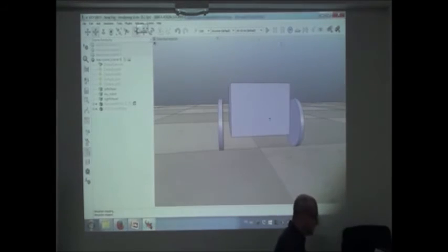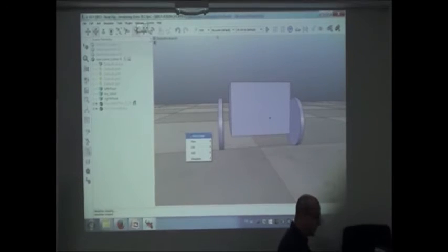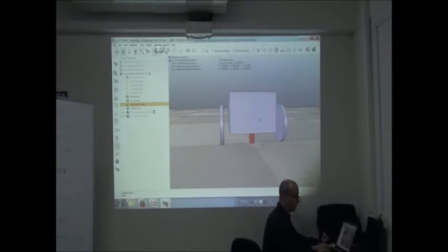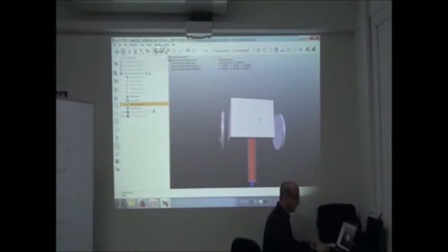So let's do that. How to add a joint? I right click in the middle of the scene, then Add, and I have something called Joint here. We want to put a revolute joint, which is a motor. Oh, look, it appears at the 0, 0 position. The only problem is that it's not oriented. The revolution axis is Z, so that's not how we want to rotate it.